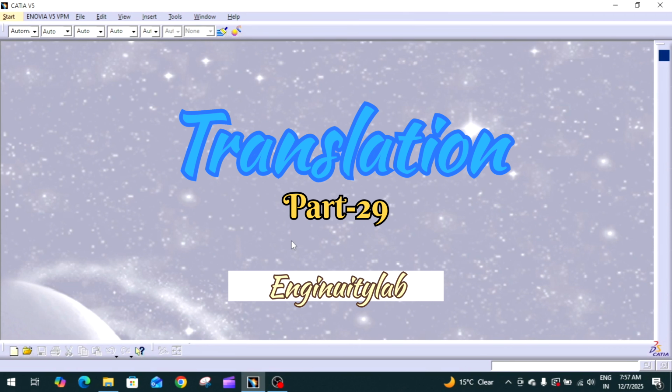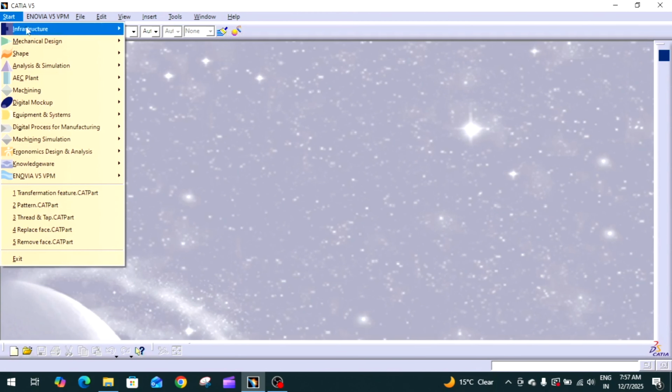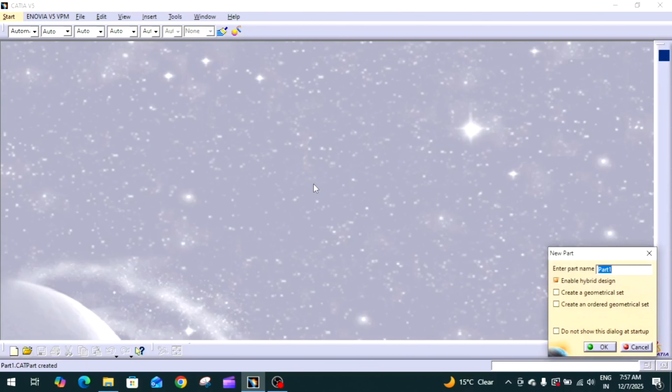In today's video, we are going to explore one of the very useful tools in CATIA V5, the transformation feature tool, the translation tool or command. So let's start. Click on Start, Mechanical Design and Part Design, rename this as translation, and click on OK.